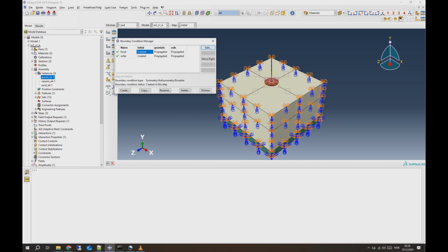And you can see this M2S1A, M2S1B, M2S1C. So we collected the experimental results from Lee et al and we compared them with the simulation results which we did. The black line here is explicit FEM, the red line is implicit FEM, and the green line is the experimental data from Lee et al. The thing is, the red line doesn't go all the way up in most of the simulations, because in implicit simulations, the model with minimum cohesion generally fails. It doesn't go through.